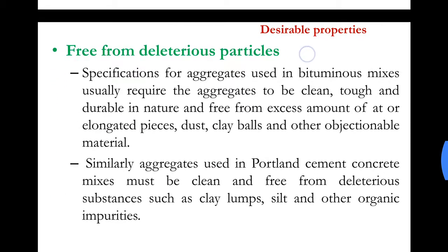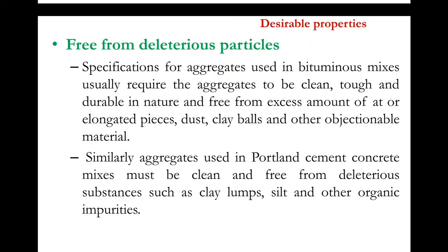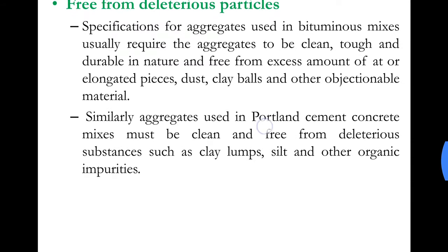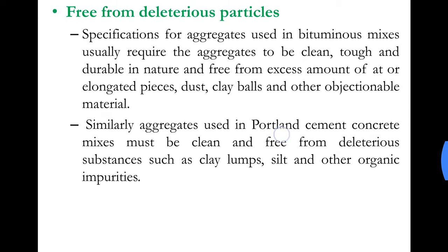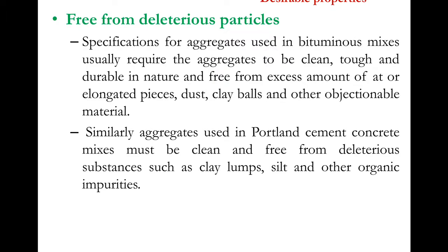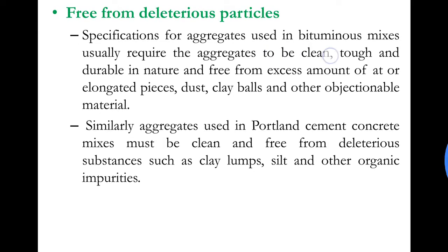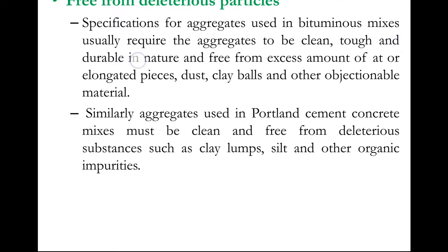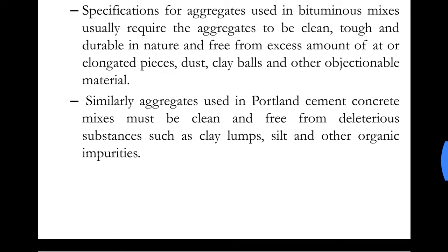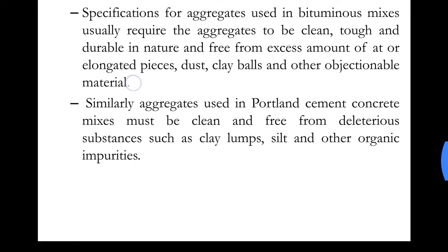The next property is free from deleterious particles. This means that there should not be any foreign matter in our aggregates. The specifications for aggregates used in bituminous mixes usually require the aggregates should be clean, tough and durable in nature, free from excess amount of elongated pieces, dust, clay balls and other objectionable material.